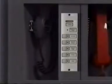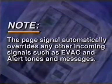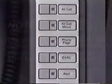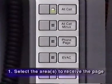Now we'll look at how to page using the 3ASU. It's important to note that the page signal automatically overrides any other incoming signal such as evac and alert tones or messages. First, you'll want to select the areas to receive the page by pressing the appropriate page function switch or switches.